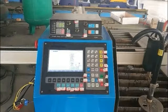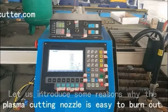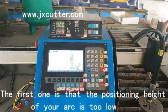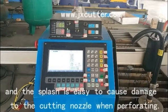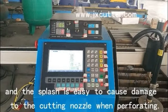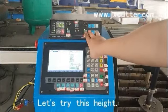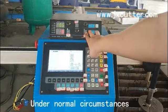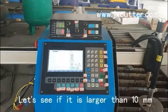Let us introduce some reasons why the plasma cutting nozzle is easy to burn out. The first one is that the positioning height of your arc is too low, and the splash easily causes damage to the cutting nozzle when perforating. Let's try this height. Adjust the positioning test. Under normal circumstances, we recommend that the customer set the positioning height at 10 mm to prevent splashing.